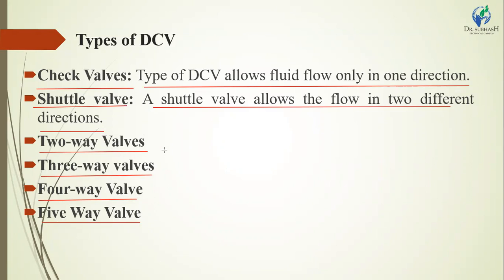If we classify according to the method of actuation, the first is manually operated: palm operated, push button operated, hand lever operated, foot pedal operated, and cam or roller operated. The second is pilot operated: single pilot valve and double pilot valve.